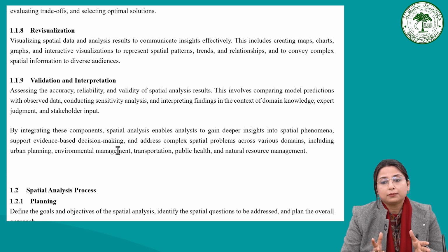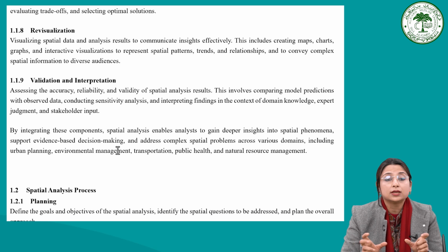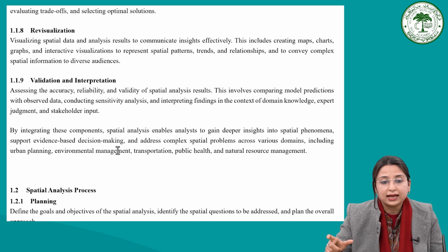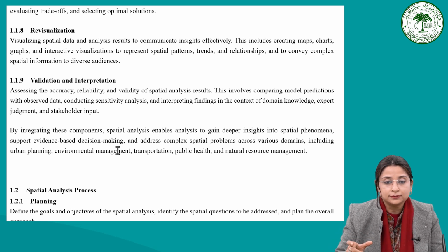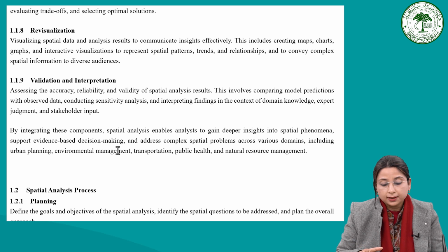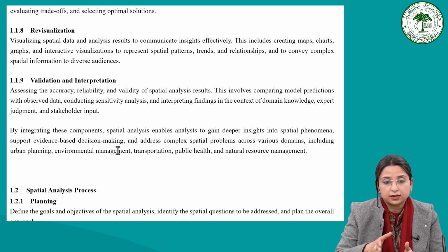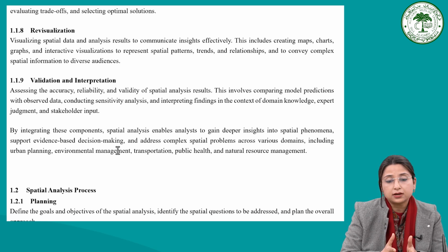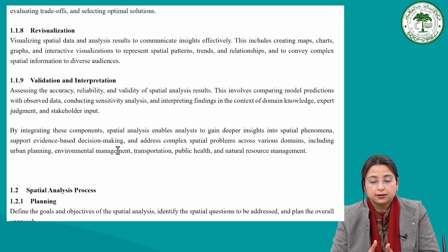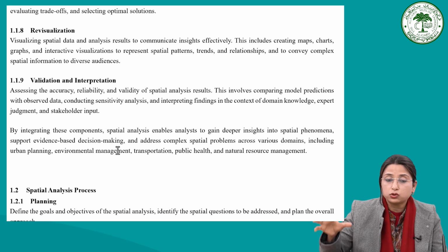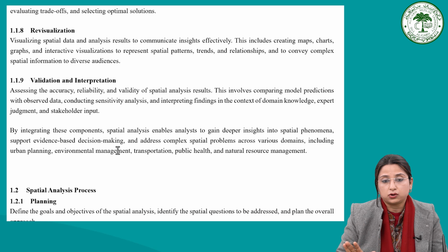How much reliable results we have received, what is the validity of that spatial analysis result. So this will involve comparing the model predictions with the observed data. For example, if we have predicted the future land use land cover through the Markov model, so validation is to be done by running the spatial data of land use land cover present data in that particular model, and once that result is obtained, that is to be compared with the observed data. Then only we can rely whether the future result we have obtained through certain model is correct or not.